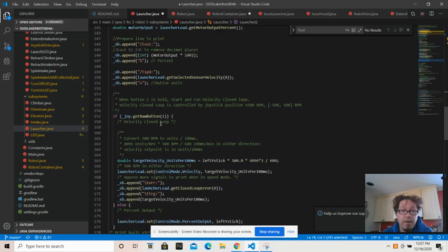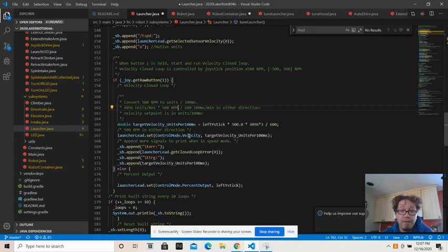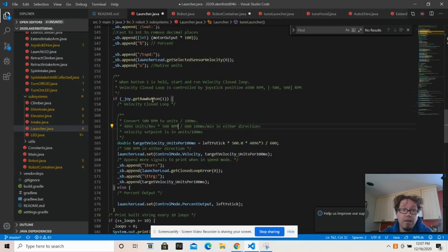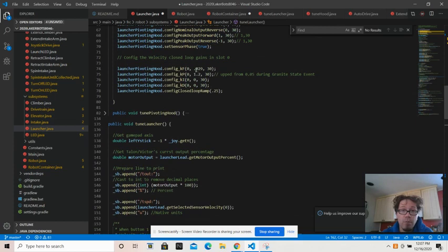And then we will push the button, and it will achieve a desired set point using the encoder as feedback to actually achieve a target velocity. And that will then allow us to compensate for any small errors with P, I, and D. Most of the time, feed forward looks pretty good and will only have a P value to correct for any additional errors.